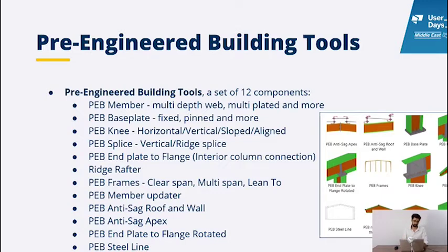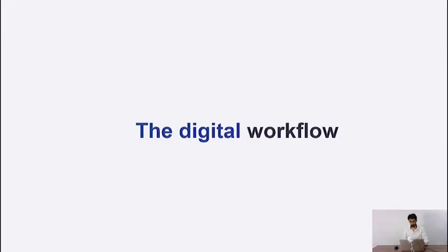But today, with the digital workflow, you start your job in MBS in the design phase. You finish it there, because MBS is definitely the leading software for designing the whole building, costing, and detailing. You complete it there, then you click that little button. It will transfer the whole building into Tekla Structures, which will include mainframes, purlins, claddings, and connections. Everything will come into Tekla Structures in its right location.